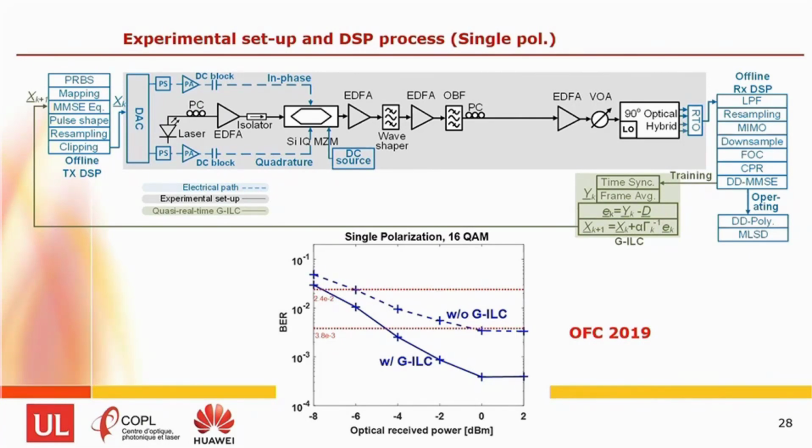And you can see for 16 QAM without the pre-compensation, applying all of the linear compensation and all of the nonlinear post-compensation, the best that we could do would get the curve in dashed. And when we introduced the pre-compensation, we had our biggest improvement. This was enough for 16 QAM to go over the 7% threshold, and for 32 QAM, it got us under the 20% FEC threshold.